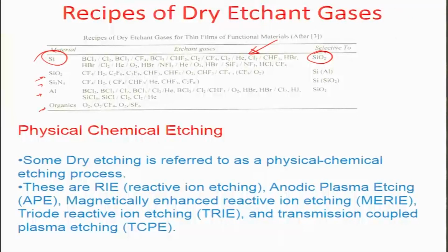So, this is also similar to a CVD reactor, where these gases are sent in at a controlled manner, and they interact with the surface and create gaseous products of material coming off the surface, and thus etch away or engrave the material in the process wherever they are exposed to or wherever the gases can attack.